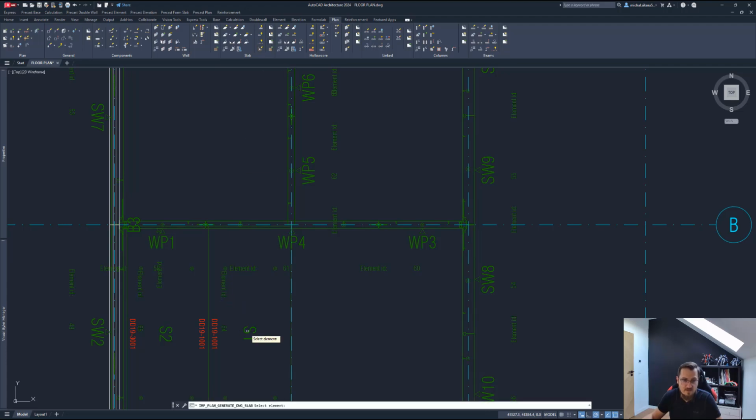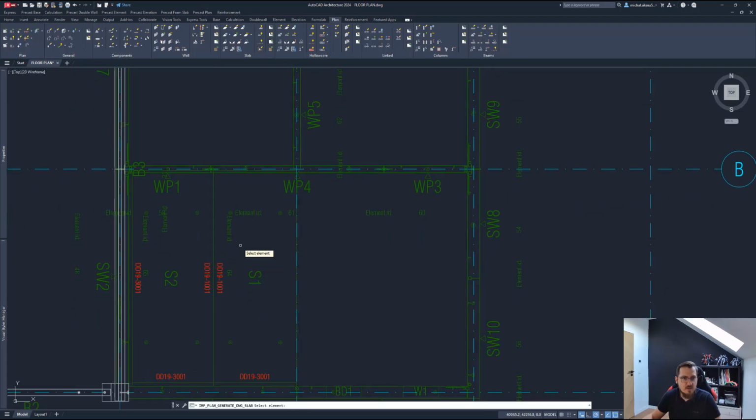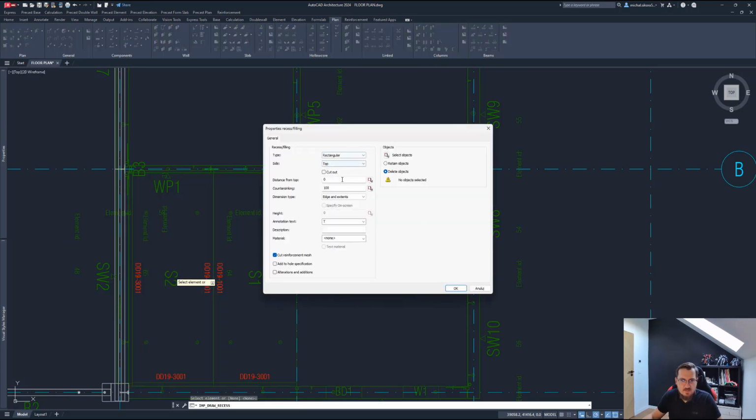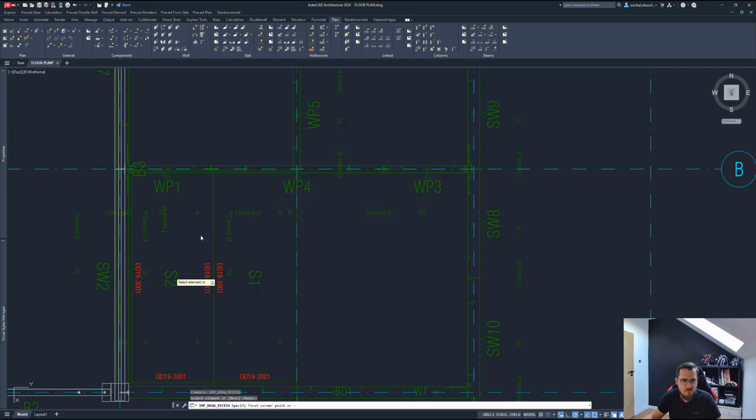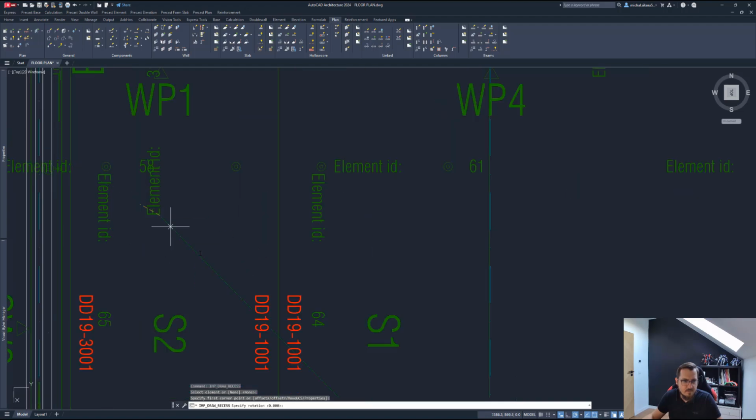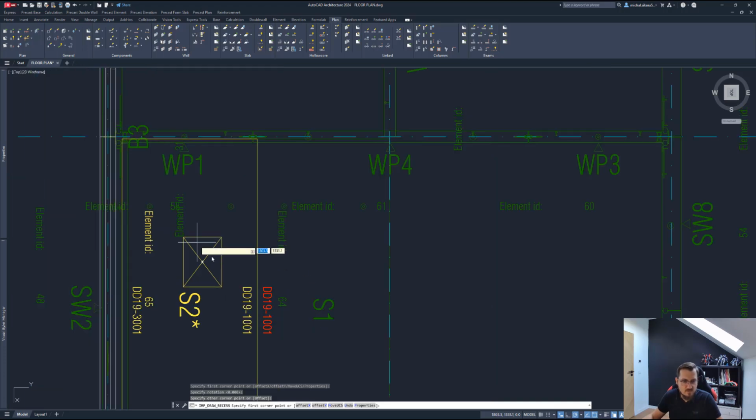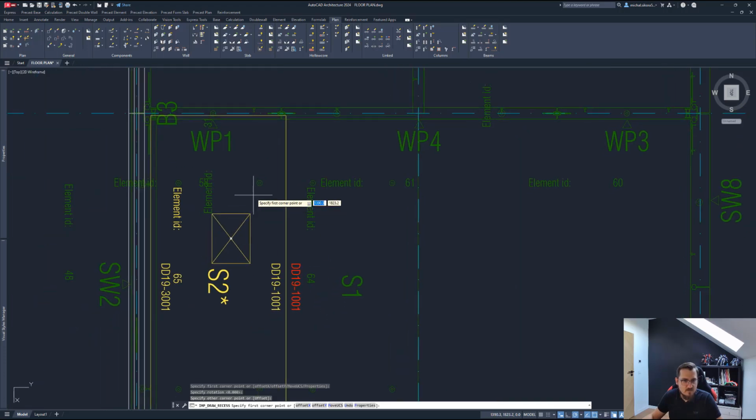You have to click the slab section. One thing we can very quickly do is create an opening in a slab. Let's select, say, this slab. Let's create a cutout and let's do that. Rectangular opening, say, like this dimension.